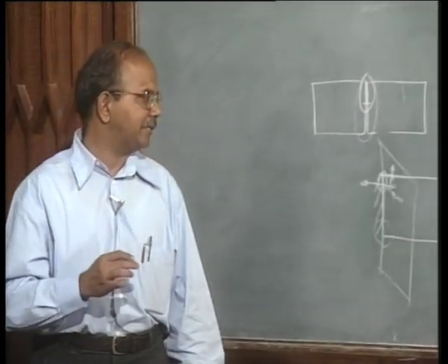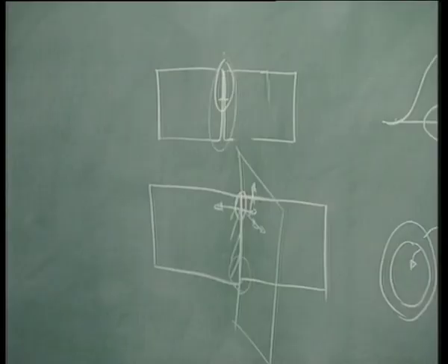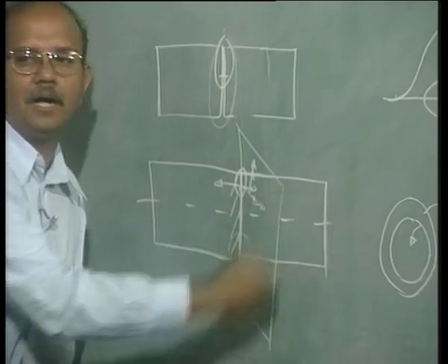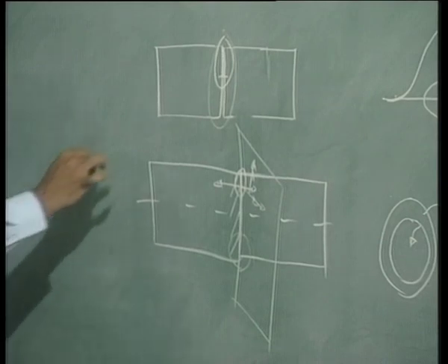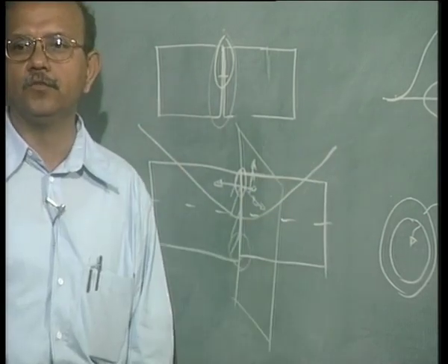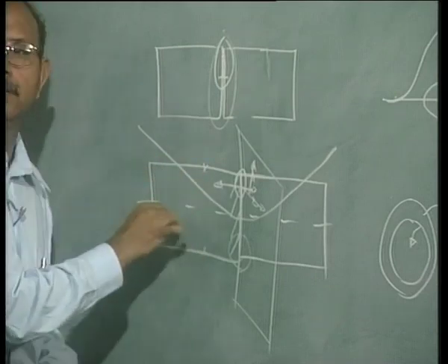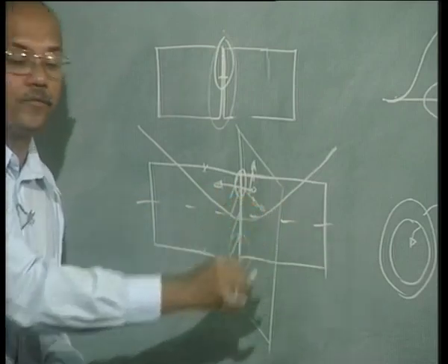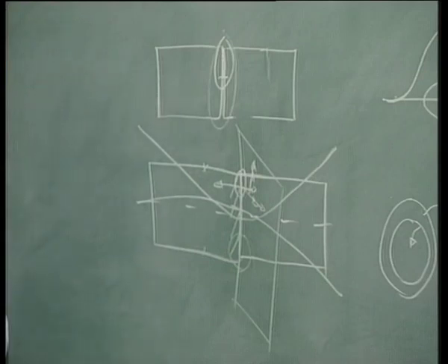See, when we say axis distortion, there are a lot of disadvantages to considering symmetry. Suppose there is an axis like this. Now how does the deformation or distortion take place? Does it become like this, in which case there is no problem? On the other hand, many people hold this and start welding this alone, in which case the distortion may be like this, then you cannot use symmetry.